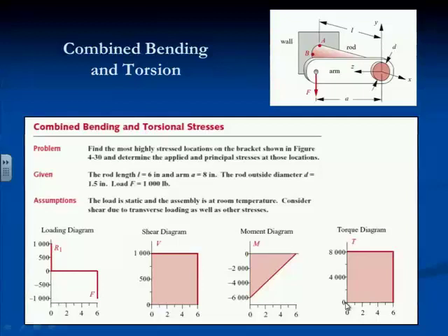Because you have, as we discussed the other day, a distribution from the top to the bottom of the beam with maximum bending stress on the top and the bottom, and it could be either plus or minus depending on which way you're loading it. Being a cantilever beam, I'm pulling down on the end, I'm stretching the top surface. This is my beam right here. So if my right hand is the wall and this is the load, I'm stretching the top surface and compressing the bottom surface, so I'd expect maximum tension here and maximum compression down here.